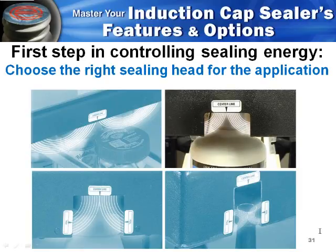In the upper right, we show a picture of our narrow tunnel sealing head. We actually create two versions of our standard tunnels, a narrow tunnel and a wide tunnel. We use the narrow tunnel to seal closures up to 38 millimeters in diameter, often used with flat or continuous thread caps, child-resistant closures, and sometimes some dispensing closures that have the foil close to the top. Our wide tunnel coil, which is the same height profile that you see here in the picture, except a little wider, we'll use to seal up to 58 millimeter closures.